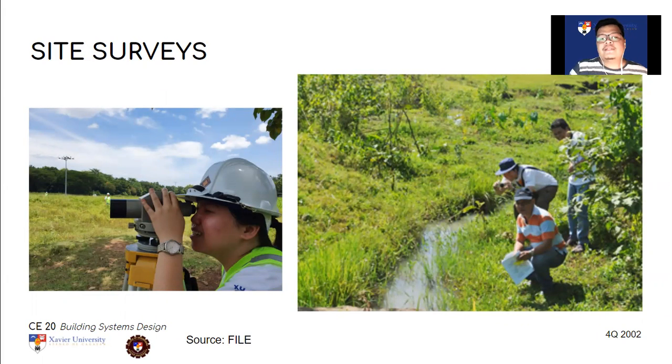In every project, it's required for an engineer, an architect, and planners to do site surveys. And we did this one rigorously when we did your surveying. Even as professional engineers, we also do site surveys. That includes checking the site for some unusual behaviors of the land. That includes location of flood zones, location of earthquake-prone zones, and even for instances where we want to plot the existing infrastructure. For a very big project, you would need to have a good background on your surveys, and that includes a detailed plot plan, which should get data from a geodetic survey.